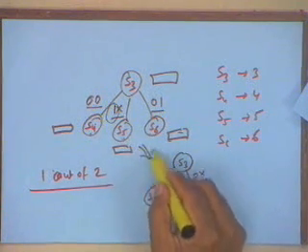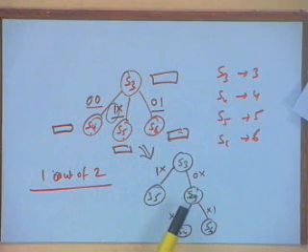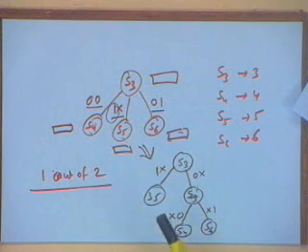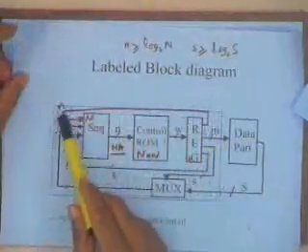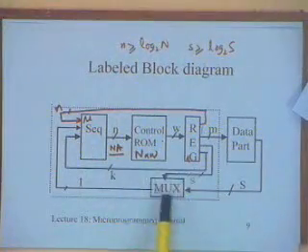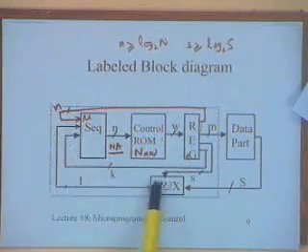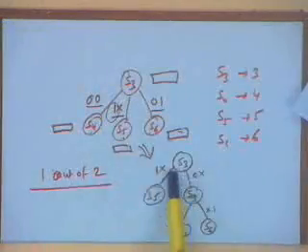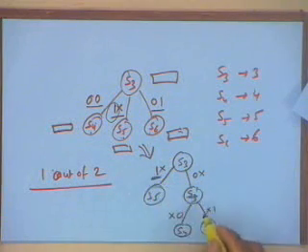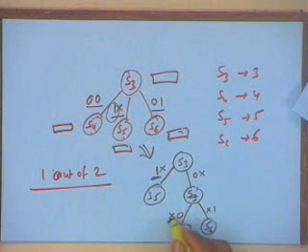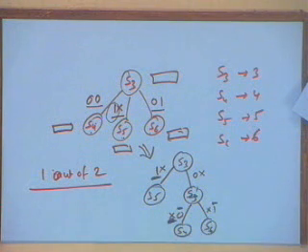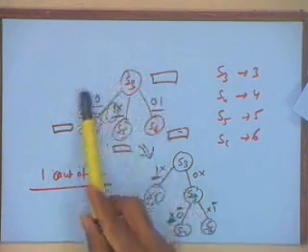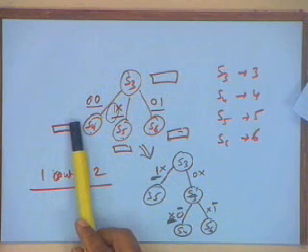So I can transform this in this manner, and the advantage of doing this is that now I am doing just a 2-way branching. I can make it so that I always either go to the next state or I go to some arbitrary state. The advantage of this is I need to supply only one address over here, which is the conditional jump address, and I need to select only one status signal. The status signal selected in this particular state will correspond to this input, and in the next state to the second input, and I can write it as a 2-way branch.